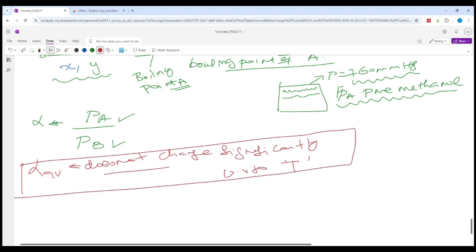we are going to make some assumptions that looks like this. I am going to assume the relative volatility won't change by a lot with respect to the temperature. Yeah? Because when you're going to deal with the distillation column, you will have so many stages and each stage will have a different temperature, and we are going to assume that relative volatility in each of the stages does not change by a lot, or they almost remain constant, approximately equal to alpha average.